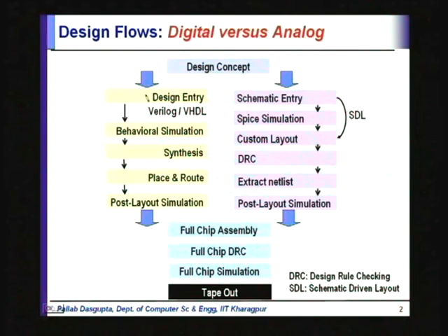Then once you are satisfied that yes, the code that I have entered is correct, then you go through the synthesis phase, in which the code is actually translated down into the design having your gates and flip flops, etc. And then after synthesis, the different blocks, the different modules are placed on the floor of the chip, again in a symbolic way. I mean, we still do not have the silicon at this point of time.